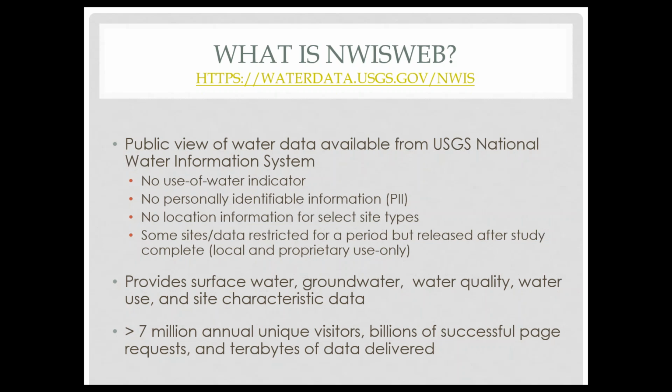It's not like when I take a water level, I'm getting an accurate water level that represents the aquifer system, if the well maybe is at an angle or not well constructed, the screen is not open. All those things you kind of need to know before you include existing wells in your study.